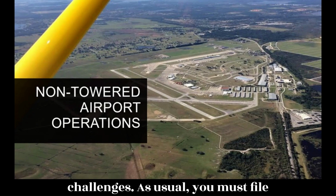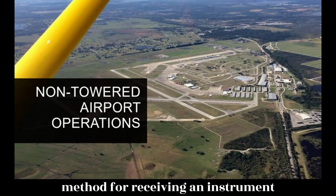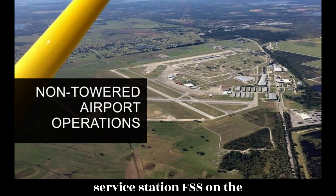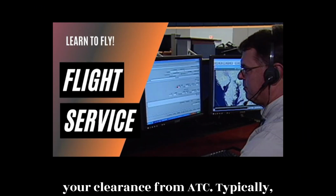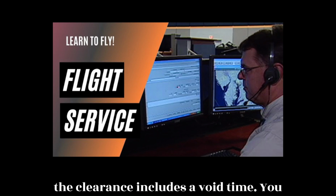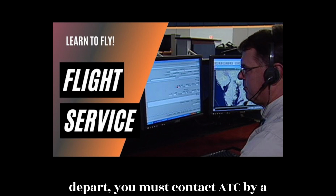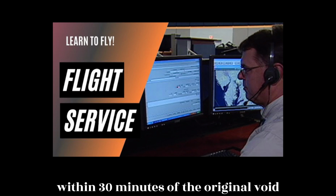As usual, you must file your flight plan at least 30 minutes in advance. During your planning phase, investigate the departure airport's method for receiving an instrument clearance. You can contact the Flight Service Station, FSS, on the ground by telephone, and they will request your clearance from ATC. Typically, when a clearance is given in this manner, the clearance includes a void time. You must depart the airport before the clearance void time. If you fail to depart, you must contact ATC by a specified notification time, which is within 30 minutes of the original void time.